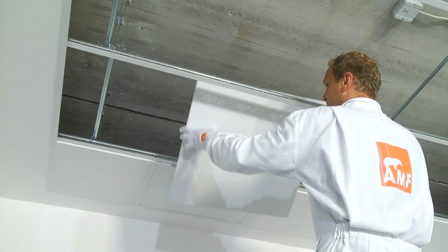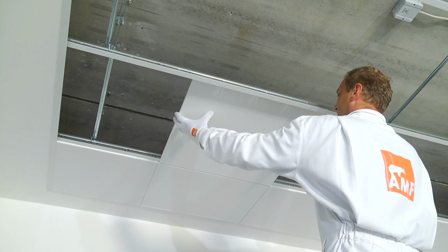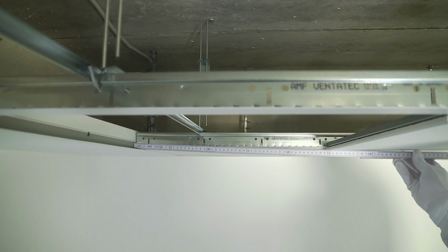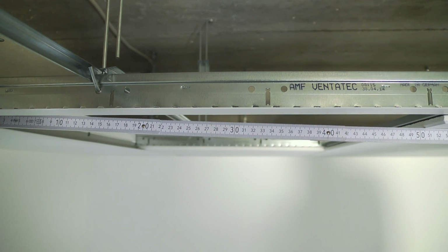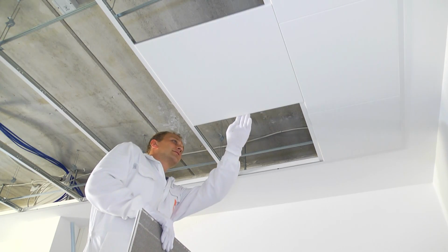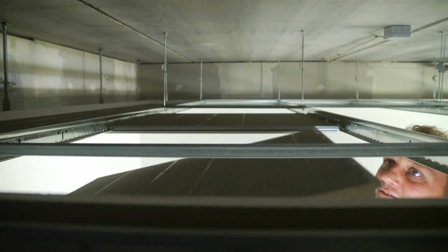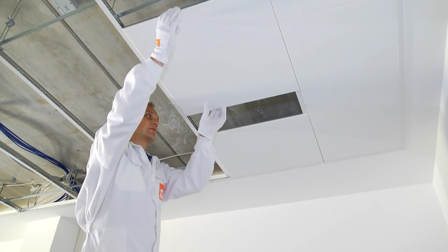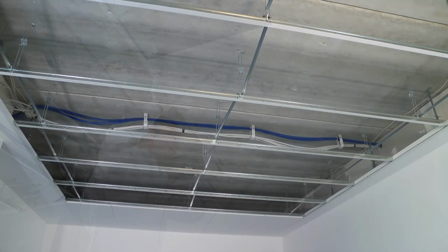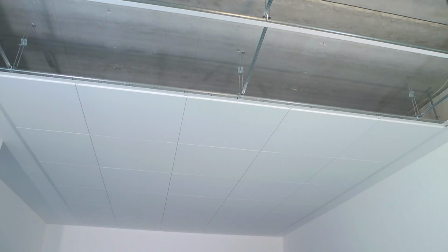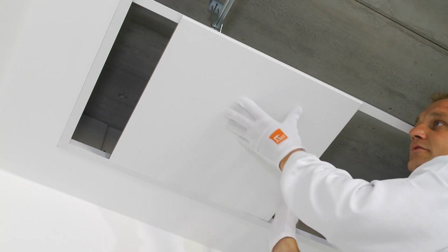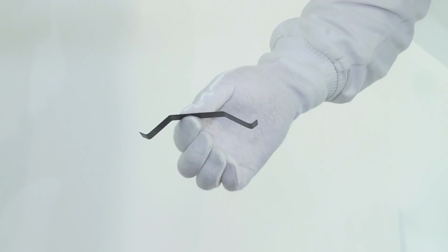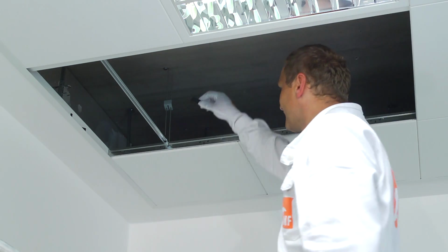The first full tile is then aligned and installed exactly in the second row. The distance to the wall is then measured at 2 points and the tiles cut exactly to fit. To install the cut tile, the tile already installed is pushed a few centimeters to the side and subsequently pushed back. The ceiling is then completed row by row. The last 2 rows are installed together to enable easier installation of the 10 mm smaller cut tiles with perimeter clips.